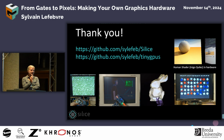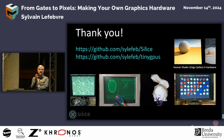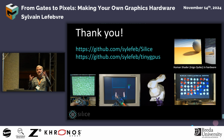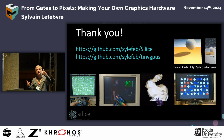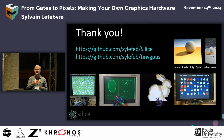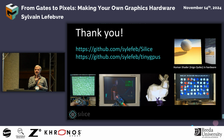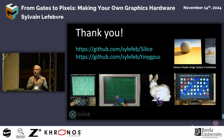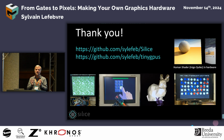That's a very good point. And in fact, there are some initiatives. There's a framework called LiteX, where in a Python script you can assemble hardware pieces, and it will generate the specific hardware and its firmware. The GPU I made is actually very simple to reuse. In fact, between the two designs, the single FPGA and the dual FPGA design, the hardware description of the core of the GPU hasn't changed at all. It's the same being reused.